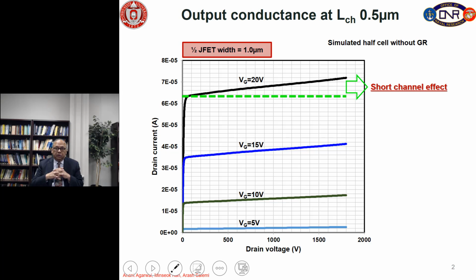So, in the last lecture, we talked about the planar DMOSFET, and we took an example of 1700 volt devices, and we calculated the epi layer thickness and doping, and then we optimized by means of simulation the JFET gap, which came out to be about 2 micron for the full cell and 1 micron for the half cell. So, today we will talk about output characteristics and how they relate to the short circuit performance, and how we can optimize the short circuit performance of these MOSFETs.